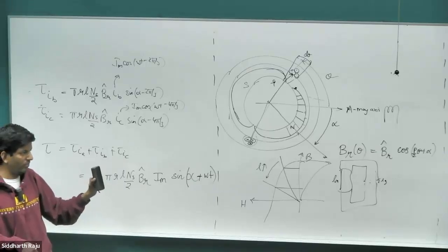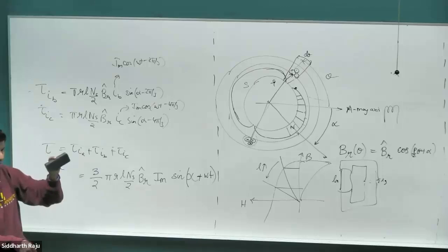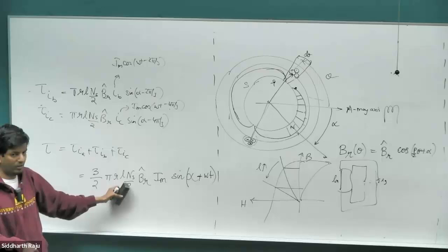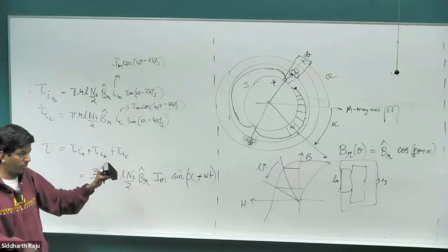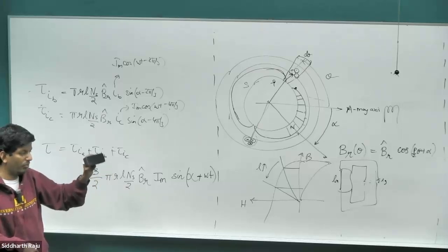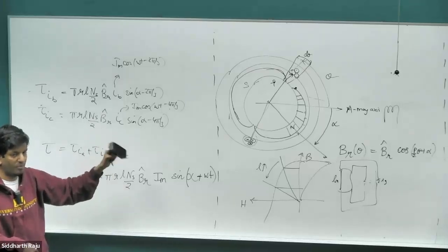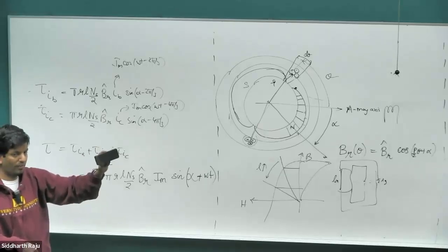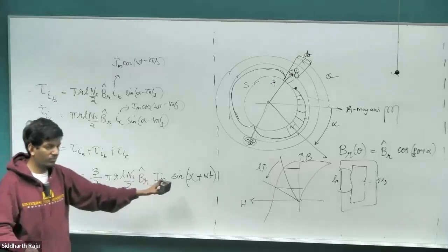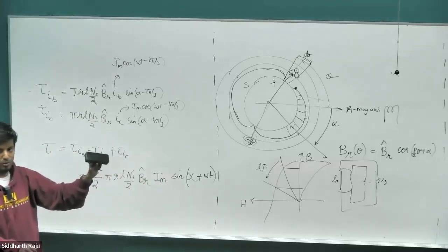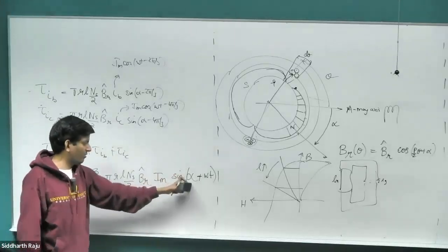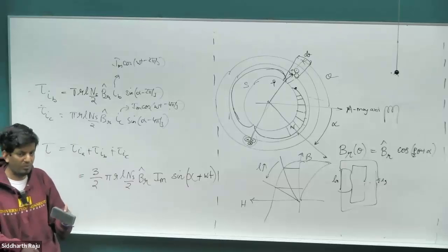Okay, so this is the biggest problem with the permanent magnet synchronous motor: if the rotor is not rotating and you apply frequencies at 60 Hertz, then the motor will not start to rotate at all because the net average torque is still 0. And this was the first problem we saw why permanent magnet synchronous motors weren't common back in the day when power electronics wasn't there, but they're becoming more common now. Because if the rotor comes to a stop because you apply a large load, then the rotor will not start to rotate again because the average torque seen by the rotor would be 0. When will the average torque not be 0? What will be the constraint on alpha for the average torque to not be 0?